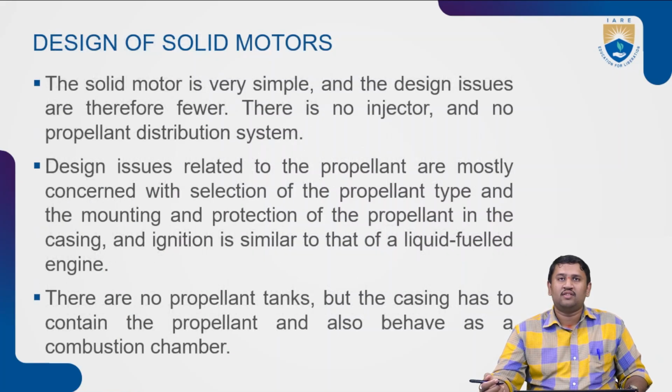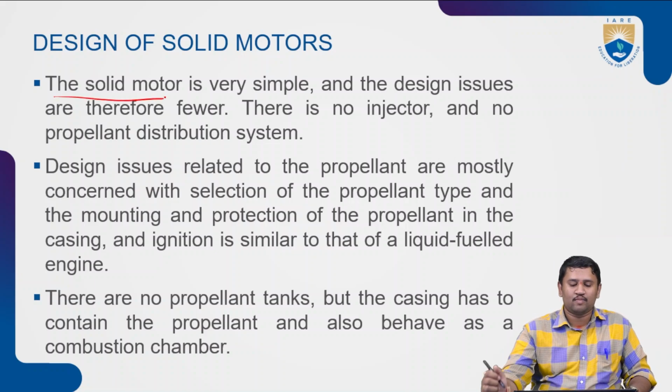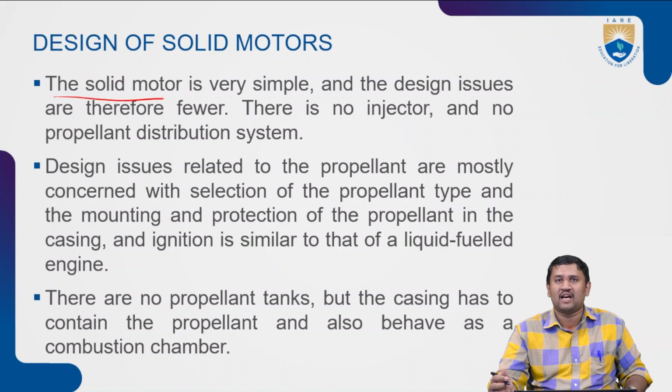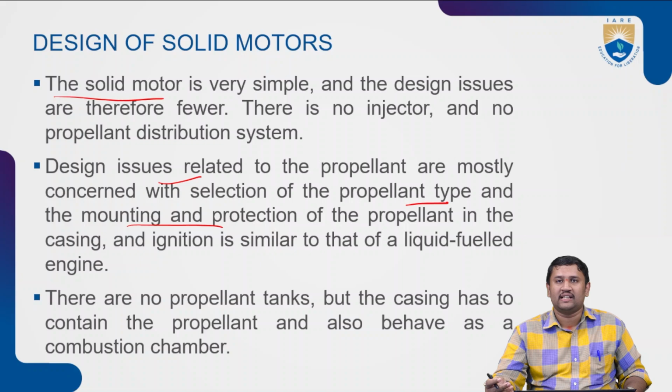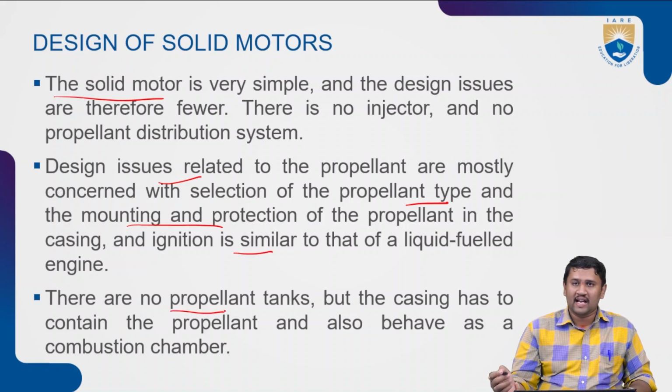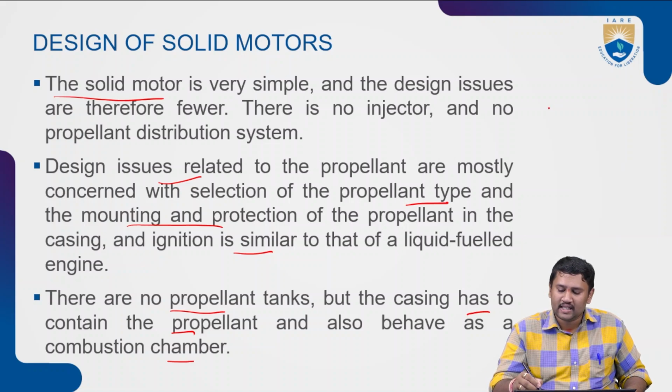Now, we will go through the steps or the method by which we will be designing a solid rocket motor. The solid rocket motor is very simple and the design issues are therefore fewer because there is no injector or propellant distribution system. The design issues related to the propellant are mostly concerned with the selection of the propellant type, the mounting and protection of the propellant in the casing, and a small ignition system similar to the liquid fueled engine. There are no propellant tanks, but the casing has to contain the propellant and also behave as a combustion chamber.